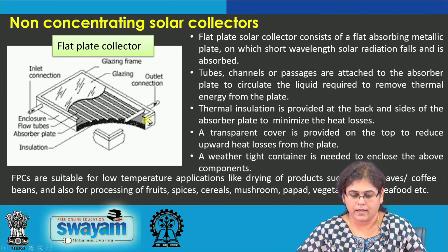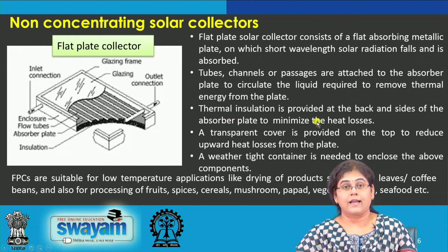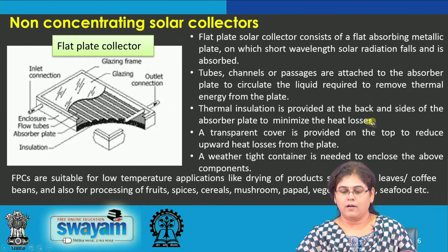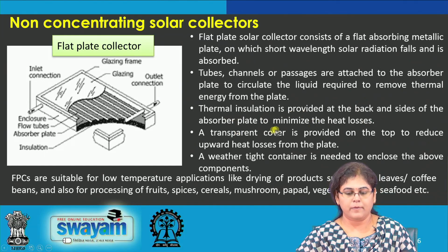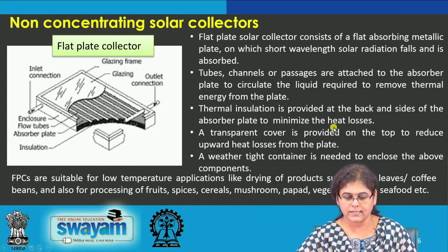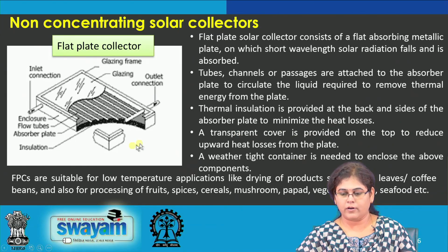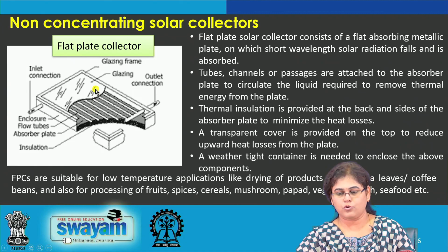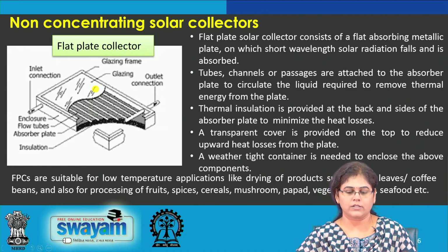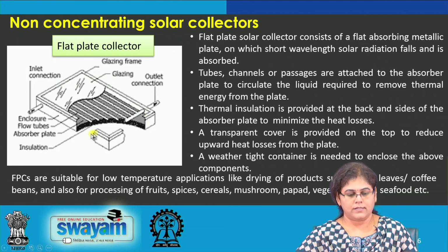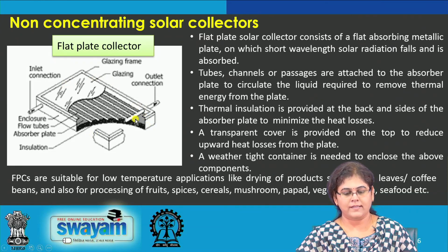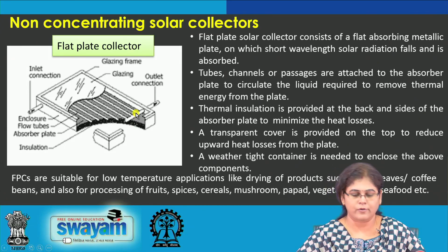Thermal insulation, as I have already mentioned, is provided at the back and sides of the absorber plate to minimize the heat losses, and a transparent cover on the top to reduce upward heat loss from the plate. So, the whole of this system is encompassed inside a weather tight container in order to prevent it from adverse weather